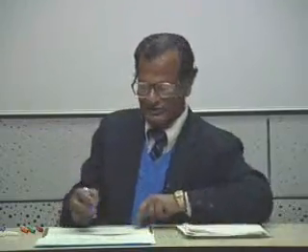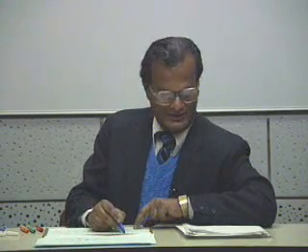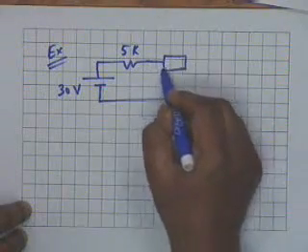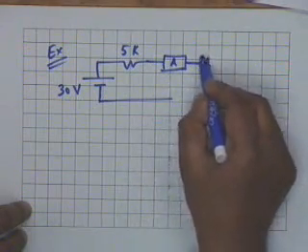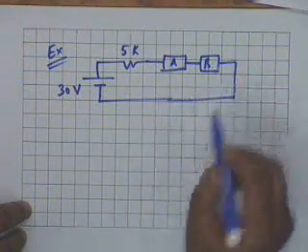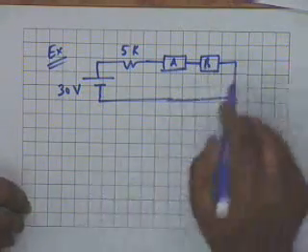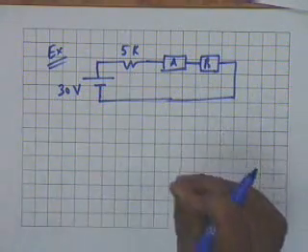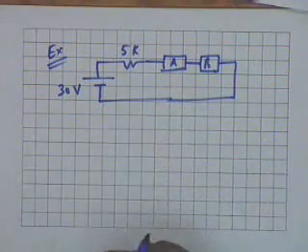And it is in this context that we shall take a fairly non-trivial example. This example concerns the series connection of two nonlinear resistors, a 30 volt source in series with 5K. This is connected in series with two nonlinear resistors A and B. The characteristics of both A and B are given.